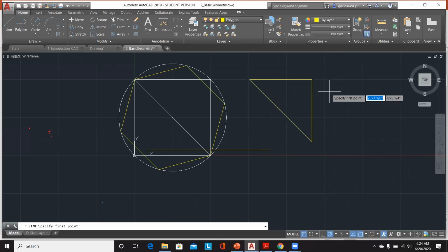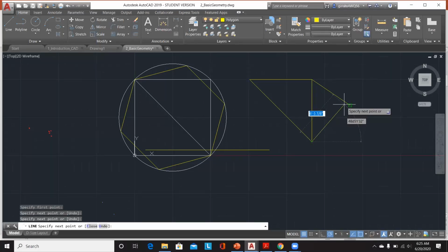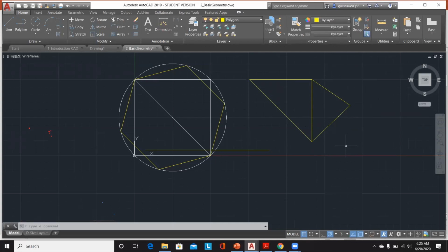If we want to make a drawing with reference to one or more points, you can select one point and not click it with your mouse, and then select another point and not click it with your mouse, and then you can click the first point and add reference to your selected points using the hover feature. So this will let you control the reference points for your modeling space or creating line segments.